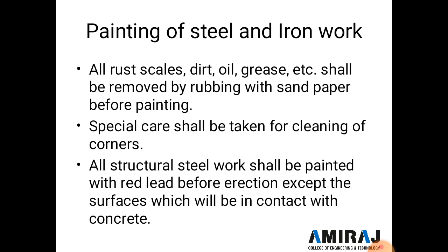Now the next important point is the painting of steel and iron work. All the rust, scale, dirt, oil, grease, etc. shall be removed by rubbing with sandpaper before painting, and special care shall be taken in cleaning corners. All structural steelwork shall be painted with red lead before erection, except the surface which will be in contact with concrete.